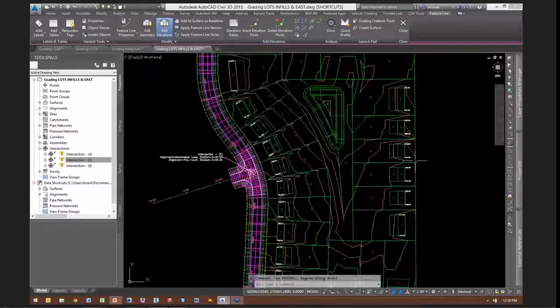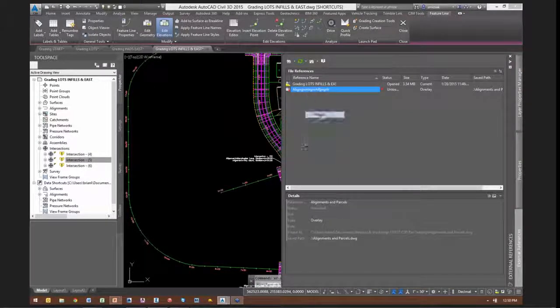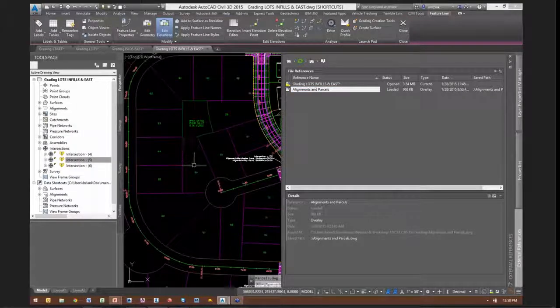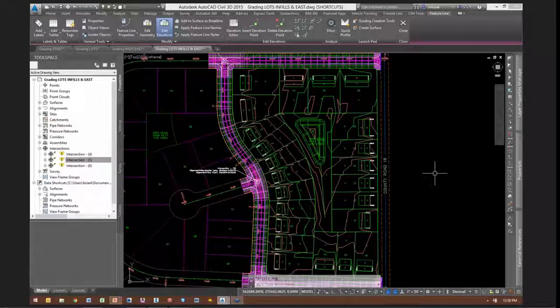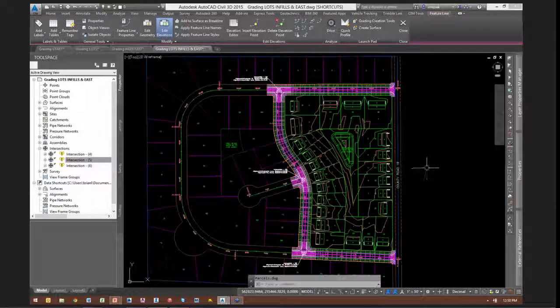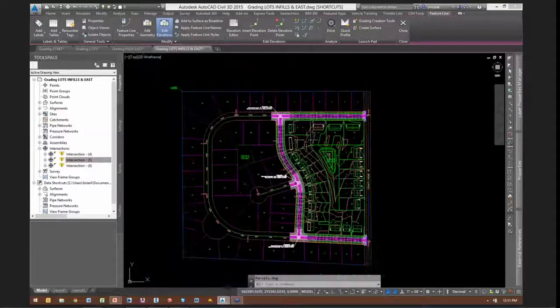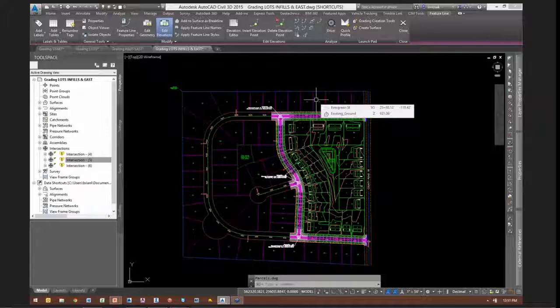So zooming out a little bit, I turn on my XREF. How do you do this for a larger development? There's a limit to what you can put in a drawing, of course. And then there's behavior with sites and feature lines and infills. So for example, this area over here, this is completely surrounded by roads as well. This would be an entirely separate site, entirely separate surface, as would these perimeter lots as well. So we'd have 3 separate sites, 3 separate surfaces.